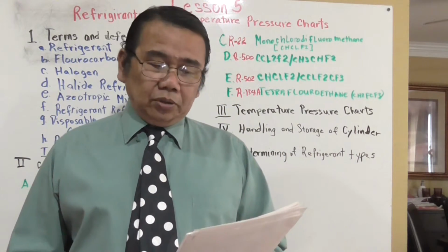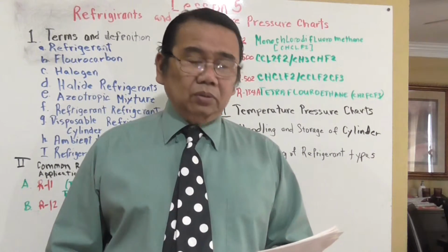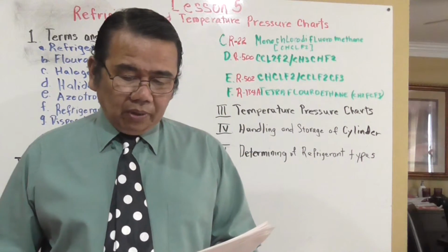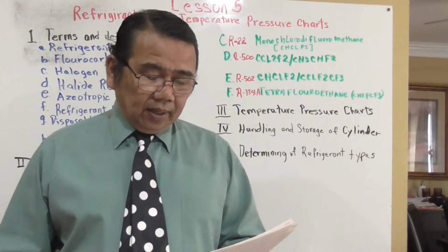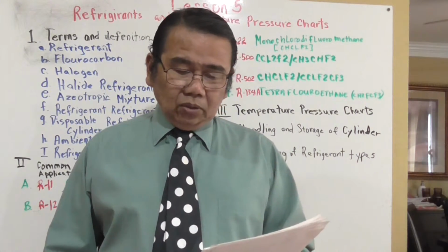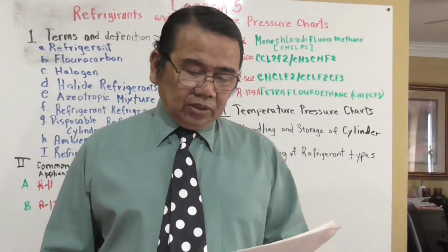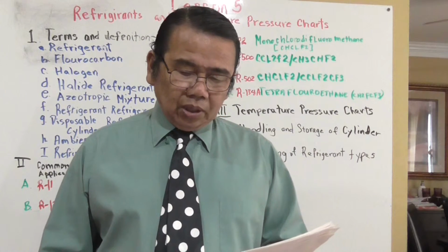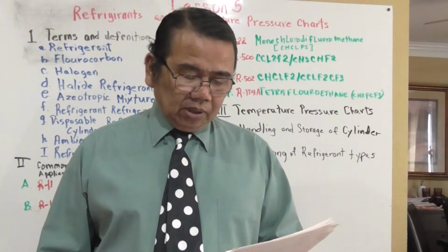This produces pressure well above the saturation pressure. The true pressure-temperature relationship exists up to the point when expansion room is no longer available in the cylinder. Extremely dangerous pressures can result under these circumstances.